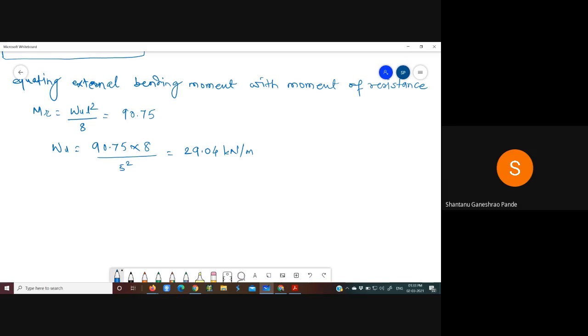You have to calculate superimposed load. Now, superimposed load means excluding self-weight. So, you have to keep in mind superimposed load means it will be totally external live load acting on the beam. So, to calculate that, from whatever WU you have got, you will have to exclude or deduct the self-weight of beam. So, first we will calculate the self-weight of beam, which has to be deducted.